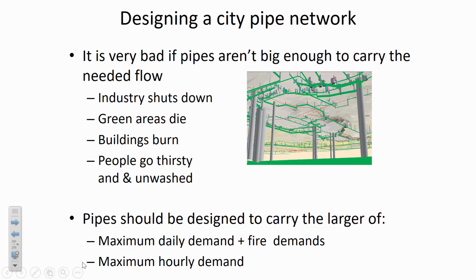But now consider, is that golf course going to be watered 24 hours a day, 7 days a week? If people are out there golfing, the water's not going to be on. They're not going to be watering the grass while people are trying to golf. And so generally what the courses will do is in the evening hours, when temperatures are lower and there's reduced wind to try and prevent evaporation, that's when the lion's share of the irrigation would occur. So you kind of need to think about when the water demand is going to occur, but then at the same time trying to construct this nightmare scenario that ensures that the pipe sizing is big enough.